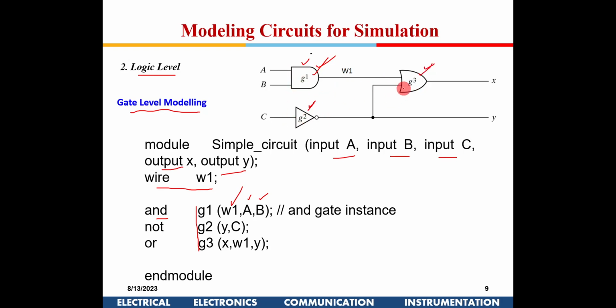This is possible. First we run a Verilog code and do a logical verification, and then we do the synthesis. When we do the synthesis, these gates will be picked up from the actual library. There are several delay models available in the library, so you can choose one of those delay models. So you can do a timing analysis at the gate level also. That is what is done in the industry today.